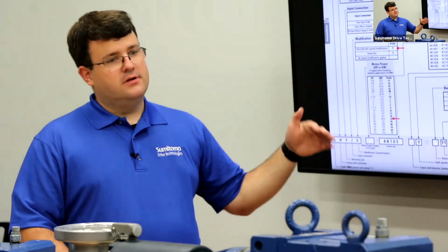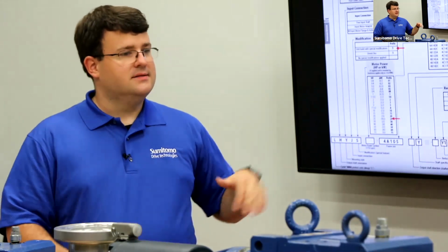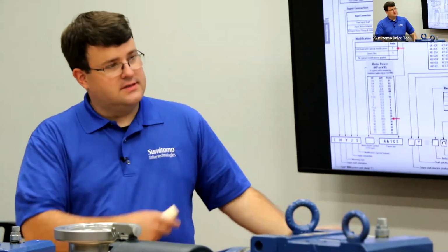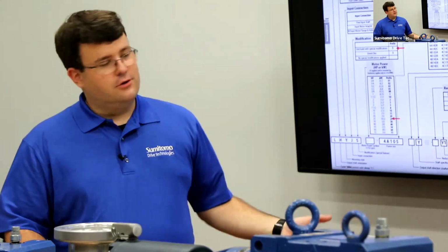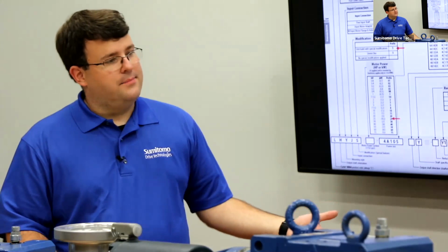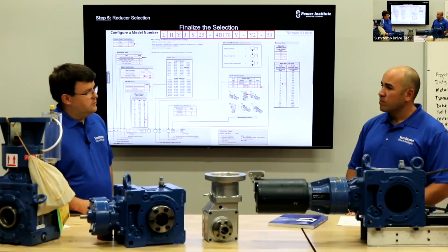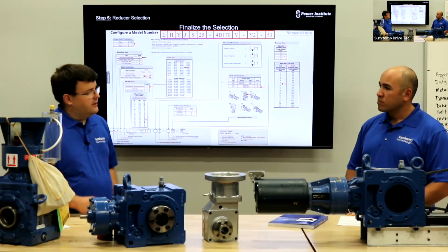It would notice that the vibration level's going up, or the motor's starting to pull more amperage than it has. It gets that trend, that history information, as I mentioned before, that nobody else is looking at or is going to record. So you can prevent that type of failure before it happens. Condition monitoring is a big thing right now, and our system will definitely help in that type of scenario.